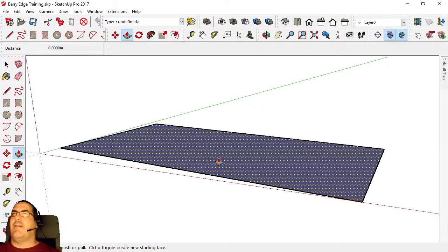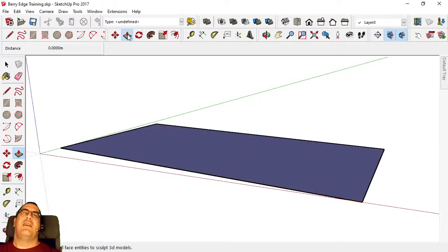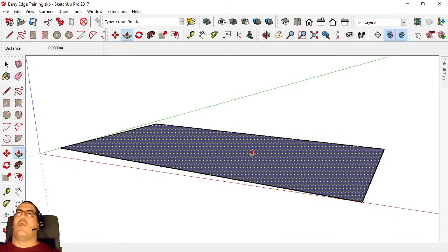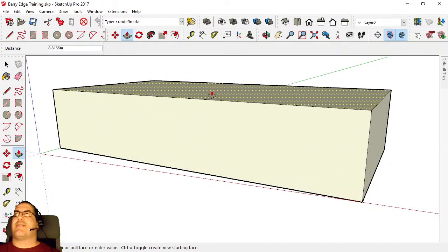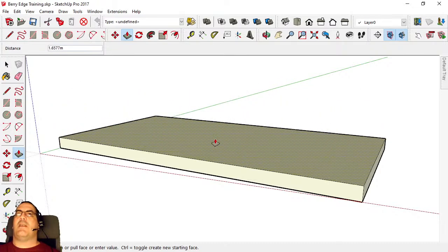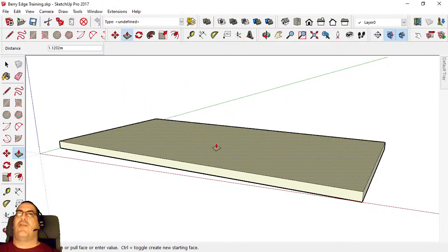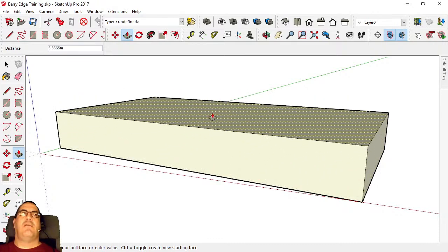So if we click, this is our push-pull tool here. This is otherwise known as extrude, by the way, for those who are wondering which one I'm using. When you hover over and a thing goes dotty colour like that, that means that your auto select's in place. So if I click on that now and just let go of the button and the mouse, if I now move my mouse up, that'll start pulling up and down. Yep, and you can see in my distance field the numbers going up and down. But you don't have to do this with your mouse and judge it by eye.